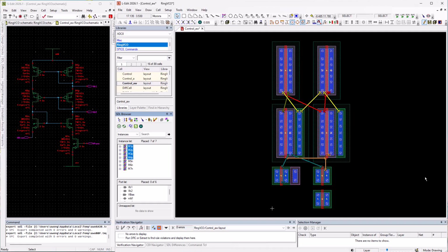From here, I can then choose the best orientations and placements for the transistors so that I can make the most direct and efficient connections. So in this example, I will want to place the P transistors so that the source string sharings can be optimized. And then for the connections from the P to the N, I will want to avoid any crossover. So let me do that.